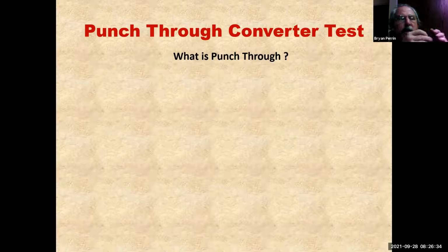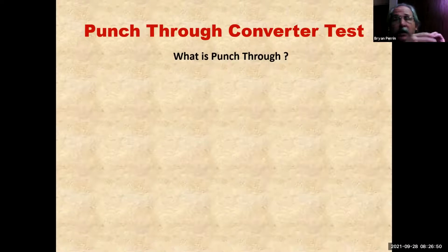That's why some modern catalytic converters, instead of having these microducts all square from front to back where you can see through it, actually twist the bed so that the gas is forced to come in contact with the sides of the catalytic monolith to force a catalytic reaction, increasing the efficiency of the converter.